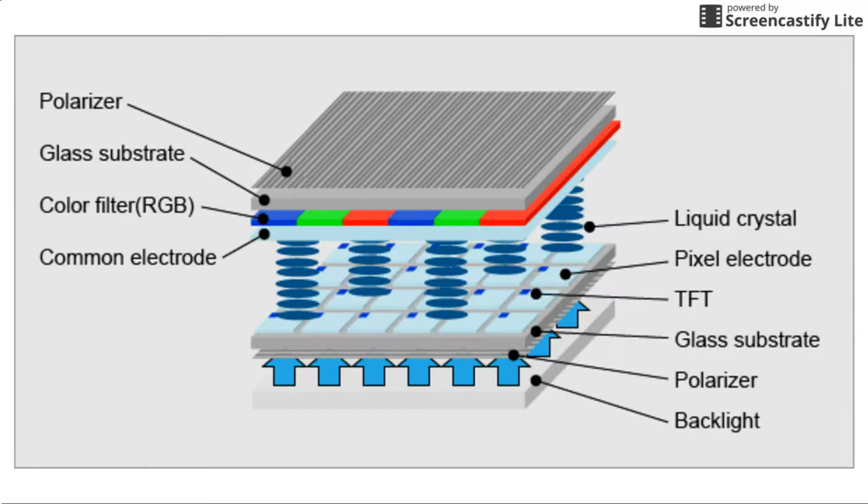a liquid crystal. A liquid crystal display is made of millions of pixels. Each pixel is composed of 3 subpixels, one for each color: red, green, and blue. Each subpixel has its own thin film transistor that varies the voltages applied at each crystal. This results in varying light transmitted at each subpixel. This allows for sharper, high-quality color images and also provides quick response times in touchscreen devices.